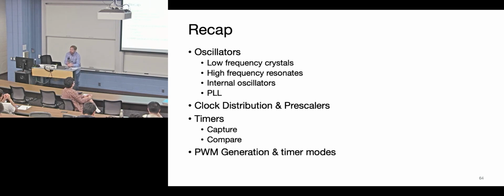Yeah. I guess just like sharing our prescaler values, those terms like how precise we want to be, and then everything else just kind of follows. Yeah, if you're setting up a pulse width modulation, you want to figure out, I guess the parameters are how long does the period really have to be? How precise do I need to have this? How many steps do I need to have? Generally in the real world, it's easy to have lots of steps and nobody really cares. It just becomes a problem when you're like, oh, I just can't go long enough because my counter doesn't have enough bits in it.